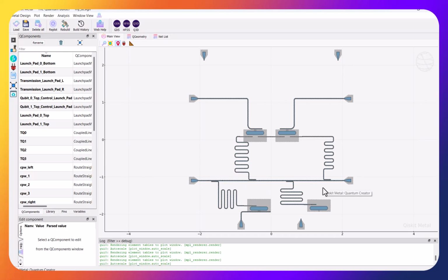So in order to do the simulation, make it faster and also less messy, before we already showed that we tried to run the eigenmode, and we showed that they're well separated. This circuit works well. So we are not going to simulate all the qubits together and all the resonators together. So we will only simulate this part.